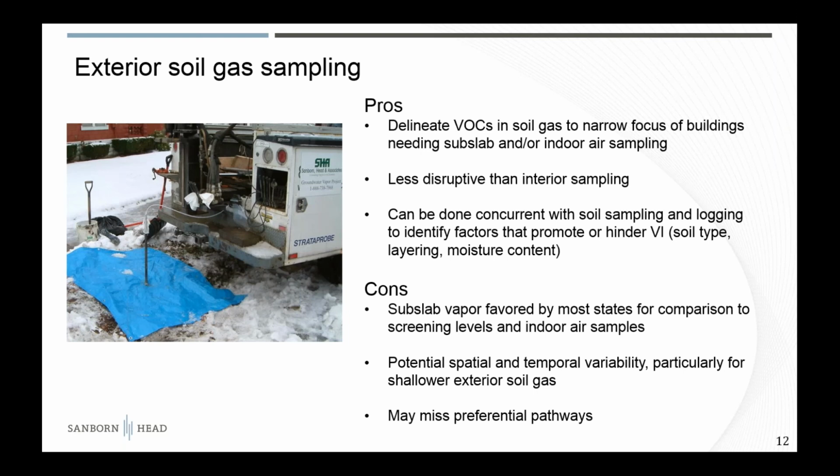There are several advantages to undertaking an exterior soil gas sampling program. This can be particularly valuable when you're getting into an initial assessment of a release in a neighborhood with a residential scenario, and you want to have a better understanding of how many homes might be affected. A soil gas sampling program can help narrow things down, so you're not just going out into the neighborhood, knocking on doors and asking to come in and drill a hole in their floor and take a sample in their house. There's some rational basis to do that, and soil gas sampling can help narrow that focus.